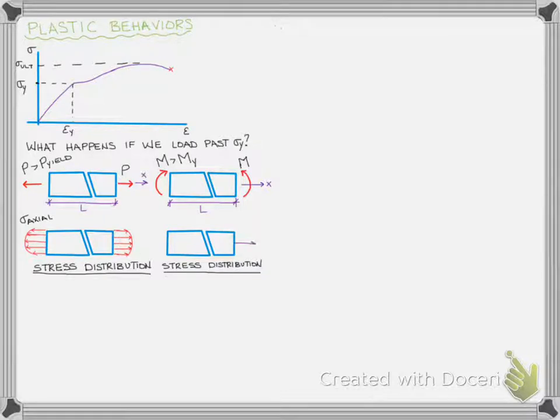When we think about the bending stress that comes from our moment, what we actually see is when we start yielding plastically, we stop having a linear relationship and we're going to see a parabolic relationship. Remember, when we found our equation for bending stress, our MC over I, we had assumed the behavior was linearly elastic, and of course it no longer is, and those equations fall apart and aren't valid anymore.